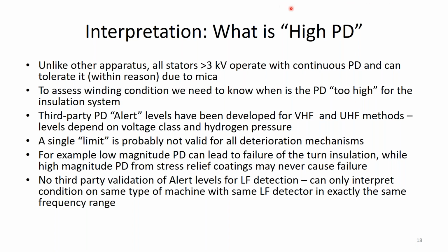Not some management person. Okay, so interpretation, one of the ways we try to interpret whether we have a problem or not is by having tables or lists or guidance on what is high PD, okay? And this is just like with bearing vibration monitoring.